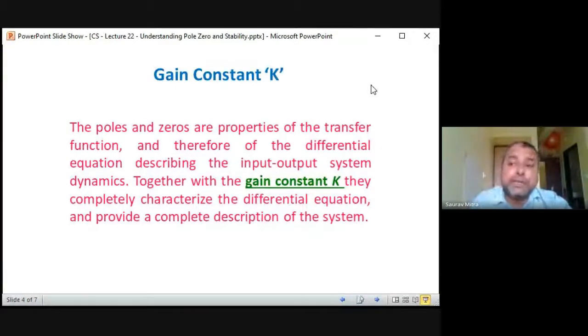K is equal to 20, you are finding the poles are on the j omega axis. And then again, if you are increasing the value of gain k, suppose k is equal to 21, you will find that the poles have just entered the positive side of the S plane, or right side of the S plane. That means the system becomes unstable. With further increment in the gain, the poles go too deep into the right side of the S plane. That means its response is exponentially increasing.